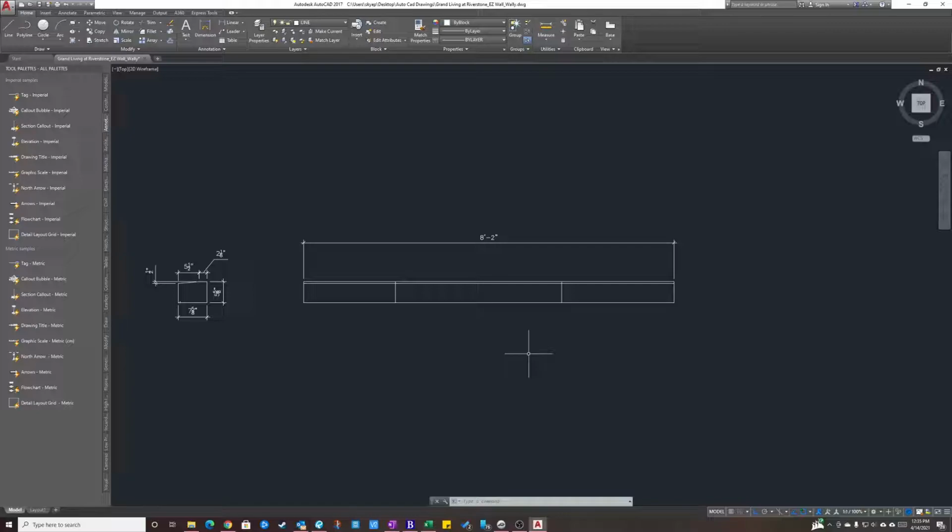So the way we figure this is we go 8'2" minus 3/4 of an inch, because that is the space of your joints. You have 2 joints that are 3/8 of an inch, times 2 is 3/4. So you take your full length, 8'2", you minus the 3/4 of an inch that you have to remove, which gives you a dimension of 8'1¼". Now you divide that by 3, because we're going to divide it into 3 pieces. That gives you 2'8" and 7/16.